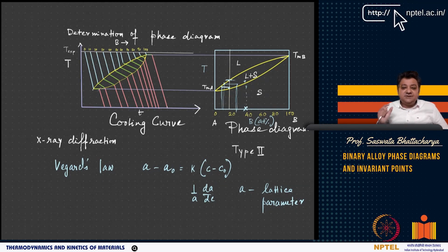Now, for each of these liquid samples, you start doing this experiment of cooling, right? The furnace cooling. As the liquid is cooling down, at one point it starts freezing. There you have this melting point or freezing point where there is a liquid-solid coexistence. However, as you know, liquid-solid coexistence for pure A will be at a different temperature than that of a mixture of A and B. And depending on the amount of A and amount of B, there will be a variation in the liquid and solid composition in the two-phase region as it cools down.